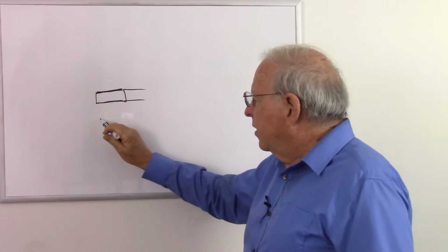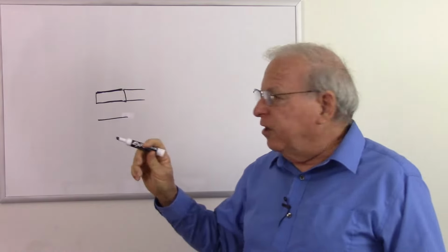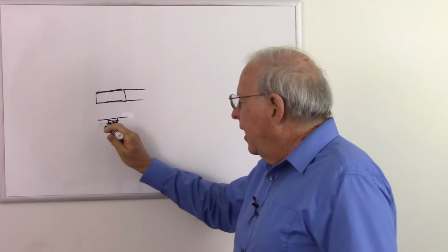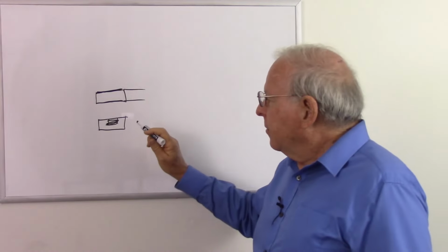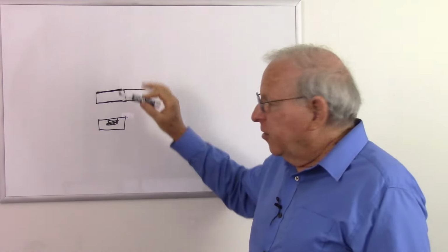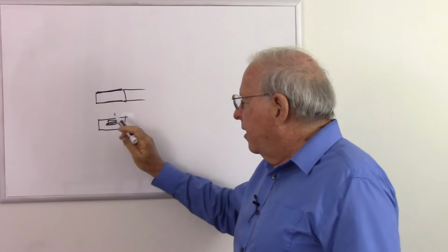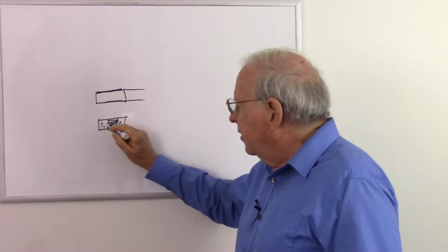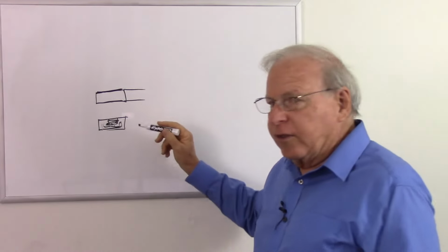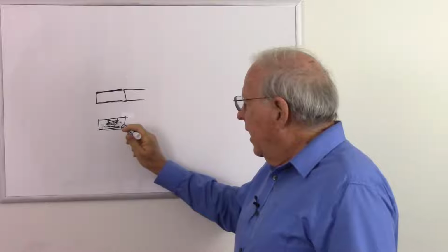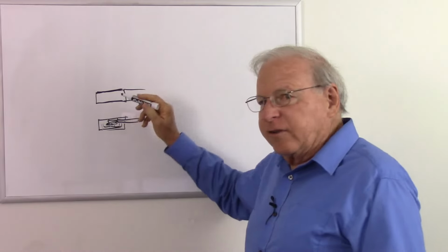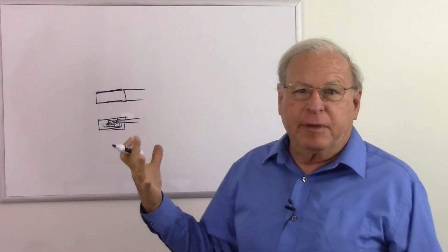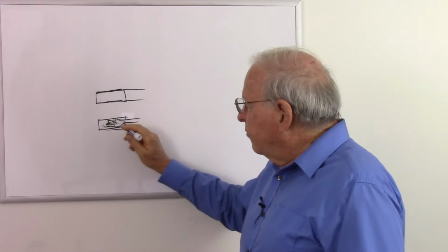And the dynamic microphone is similar in construction, just works differently. It has a diaphragm with a coil of wire attached to it. Once again, that's usually in a sealed capsule so that the air inside cannot escape. And once again, this vibrates. That causes the coil to vibrate in a magnetic field. So there's a magnet in here that goes also inside the coil, as I showed in the previous video. We pick up the wires off of that coil, and as it vibrates in the magnetic field, that creates a varying voltage, which, if we have a complete circuit, can be a varying current. And in either case, we have a sealed capsule.